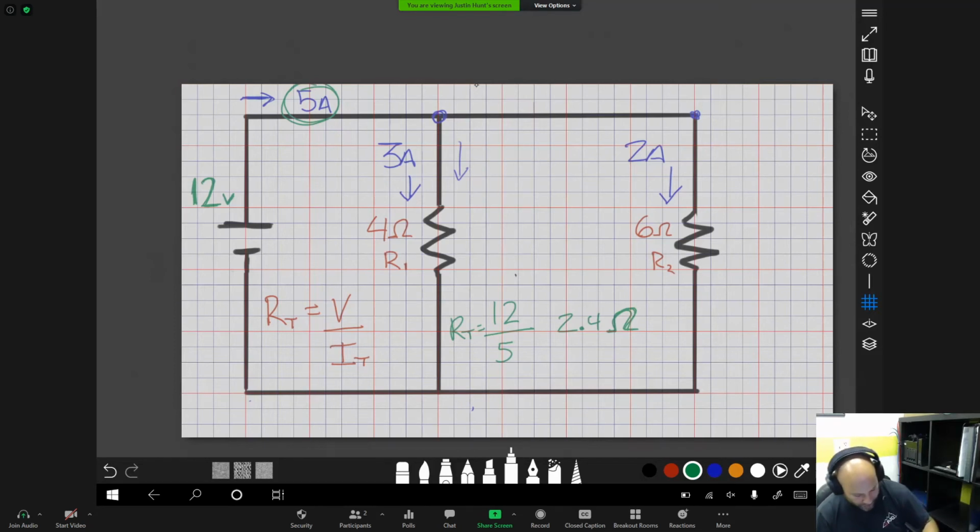We're always going to have a number that is relatively low for the total resistance when looking at any one of the individual resistances in the circuit, because we're separating the resistance between the different paths that the current could take. So if you ever have something where your total resistance is greater than one of your resistances, you might want to check your work and see where you went wrong there.